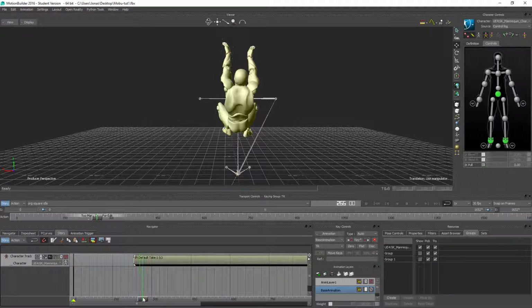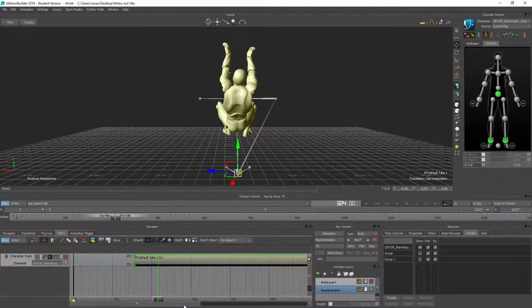Then you scrub forward a little bit, see where I start to move. So that seems to be right about here. Once you have a point in time where you think, okay, that's going to be the idling part, select it again and click the eraser tool again. That's going to divide it in two again. So all the last stuff here, we don't really care about that for now. So we're going to hit delete on that.